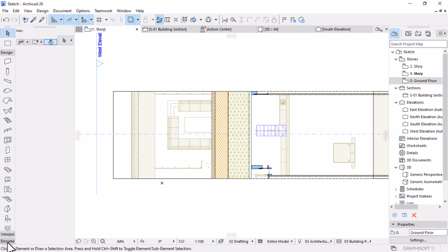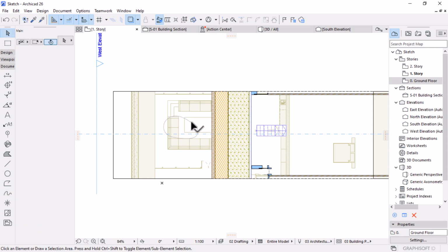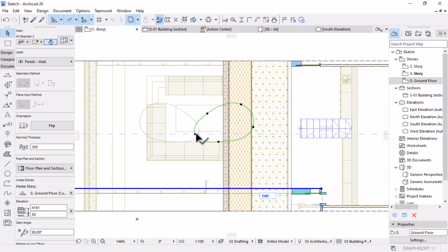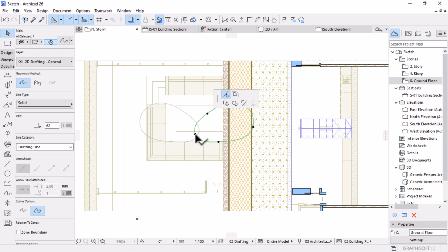So what I need to do is come here under documents and have a sketch. I would use a spline tool just to draw some shapes. Could mirror this shape, and then maybe change the geometry of this shape just to make them unique.